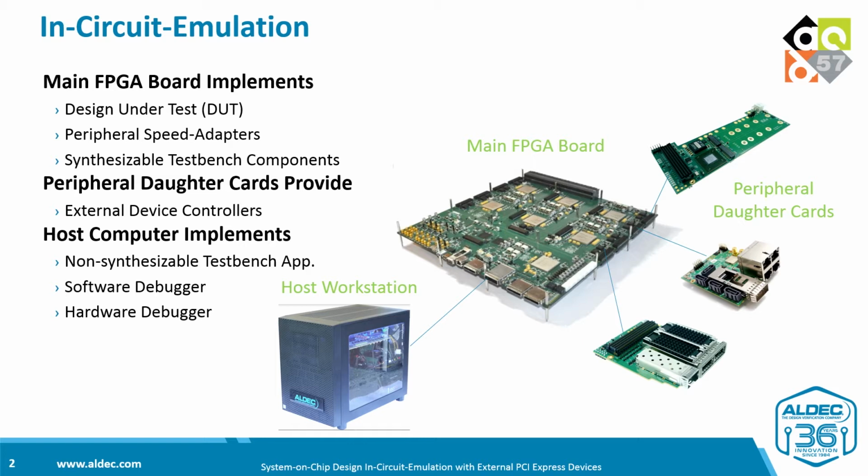So our DUT is emulated in FPGA, which means that the FPGA is not the target chip technology for our design under test. Every design has several external interfaces that are mapped to the chip I/O that serve as a communication channel with external world. That's with external devices. An inherent property of in-circuit emulation is ability to connect with these external devices that make natural operational environment for our design under test.